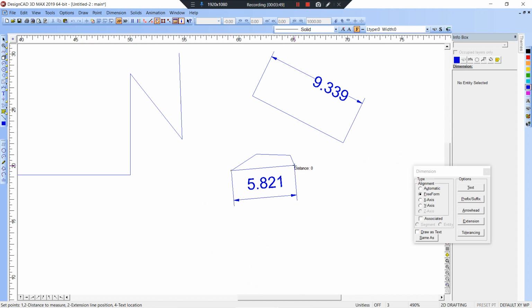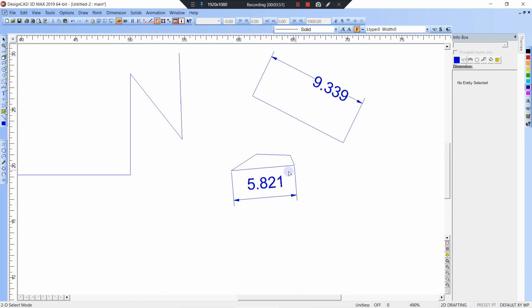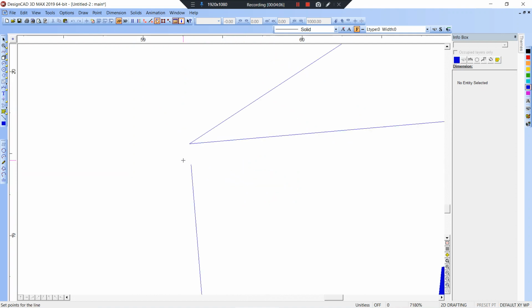Like AutoCAD, I don't know if AutoCAD's changed that too. As a habit I put everything to 0 there, but it's no longer needed. It doesn't snap to that like it's a separate entity. You can snap to that line. If you hit K, it'll snap to it. It recognizes that it's a line. If we went here, V, we snapped in K there, it actually doesn't see that there's a line there. It just kind of disappears. You can't snap to it.